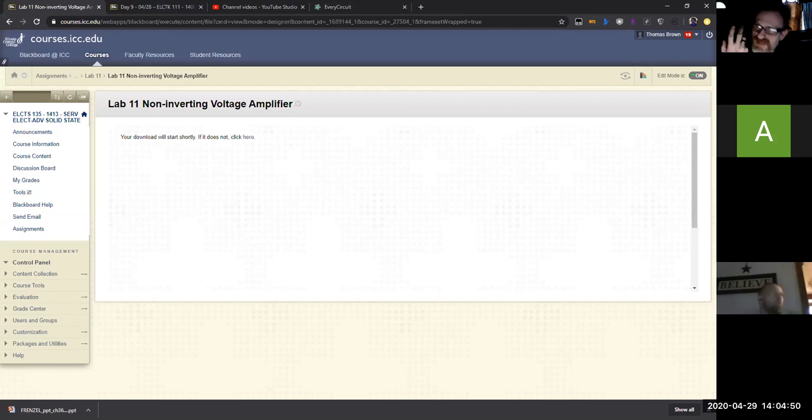But you have that lag involved always, and that response time. In the case when you need something with a quick response, you would need an active filter, like the op amp filters. If you had something like a low level signal, where you didn't need a really fast, immediate response, then you go with the passive filters. I mean, they're cheaper, right? But that's the main difference.